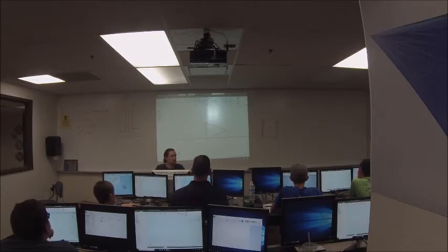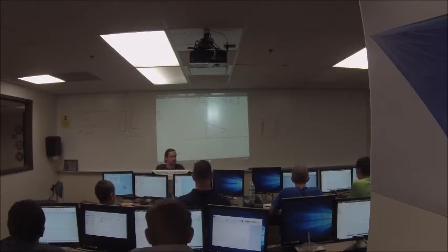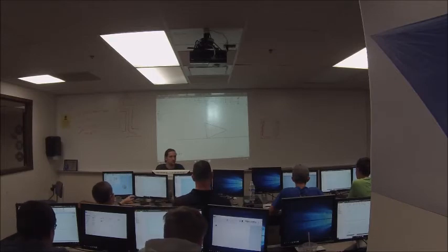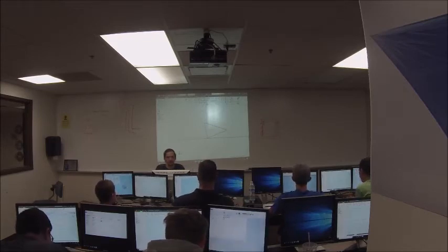What is the sequence of... The horizontal constraint. Yeah, how would I do that? How would I apply a horizontal constraint to that line? Oh. You click the horizontal constraint, and then click the one you want to then do. Click the line. So go up, click horizontal, then click the line.